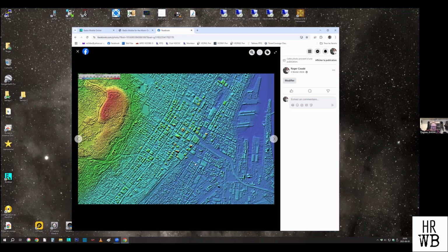That's fantastic. I would think that this level of detail would be necessary for any kind of urban radio system. It's overkill for amateur radio. Right. Unless you're doing a mesh network with Wi-Fi or things like that, but most of the calculation, as an example, it doesn't make any sense to do that with the online version dedicated for VHF and UHF. But if you're doing something like a small cell network or higher frequency point-to-point links, if you want to shoot a point-to-point link between buildings, you want to know if there's another building in the way. So this would be a good way to figure it out.